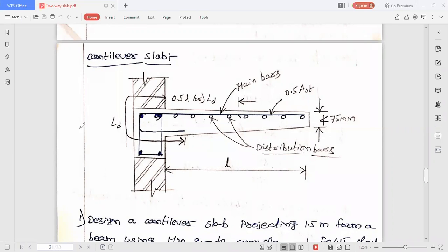Okay, exactly over the opening we will get a lintel. From that lintel the sunshade will be projected outwards. Okay, as that sunshade is fixed to the lintel and free at the other end, it is one of the examples of a cantilever slab.